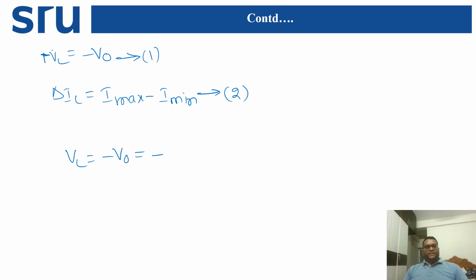When we derive the current, it goes from last value to first value, that is the case under switch off condition. The change of current will be I minima minus I maxima divided by T off. Here we need to take delta IL, which is nothing but I maxima minus I minima.